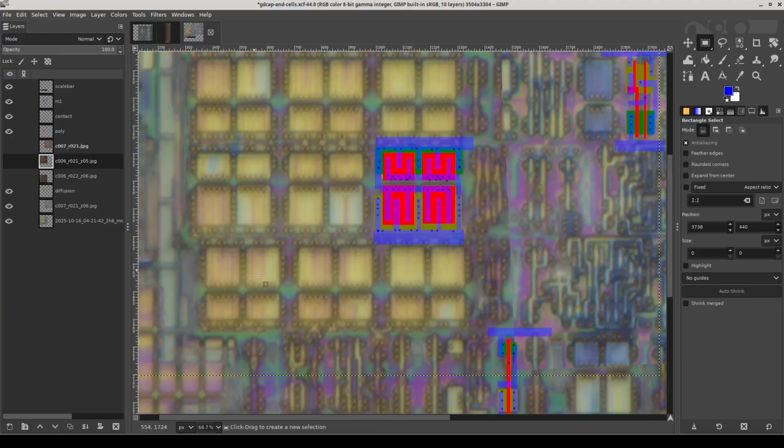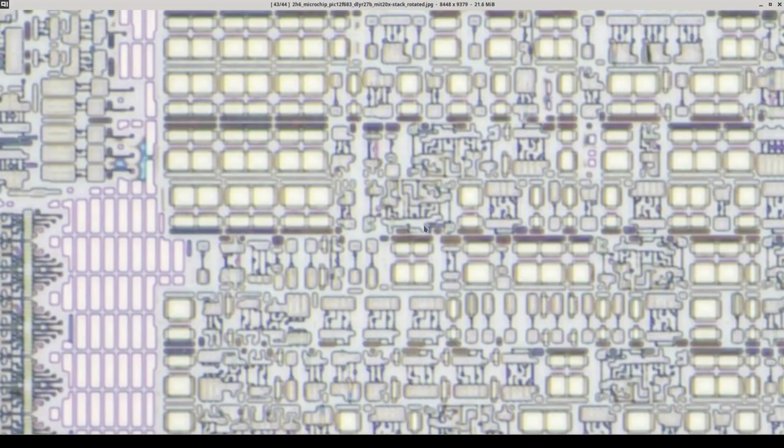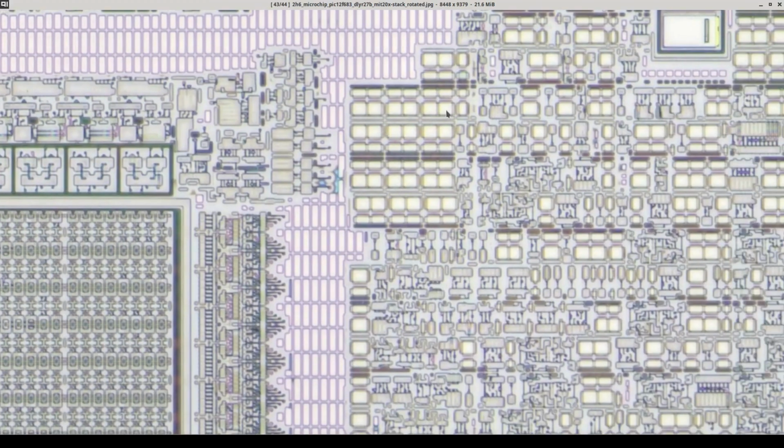As we can see, this whole area is near the edge of the array, and going back to the overview image here, we can see there's a lot of these capacitor cells on the edge of the cell area where they didn't actually need any logic. To take up space but still be able to have continuous power and ground rails, it's very common to use capacitor cells as fillers, just because the alternative would be to leave the space blank and just have a metal line there, but why would you not want more stable power?